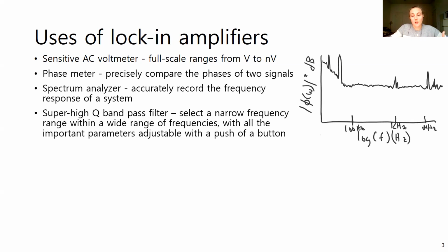To illustrate, this is a noise spectrum that we sketched out last week. As a reminder, I'll ask you, this portion here, less than 100 Hertz, what type of noise is abundant there? Pink noise, 1 over F. Yeah, 1 over F noise, so flicker noise is there.